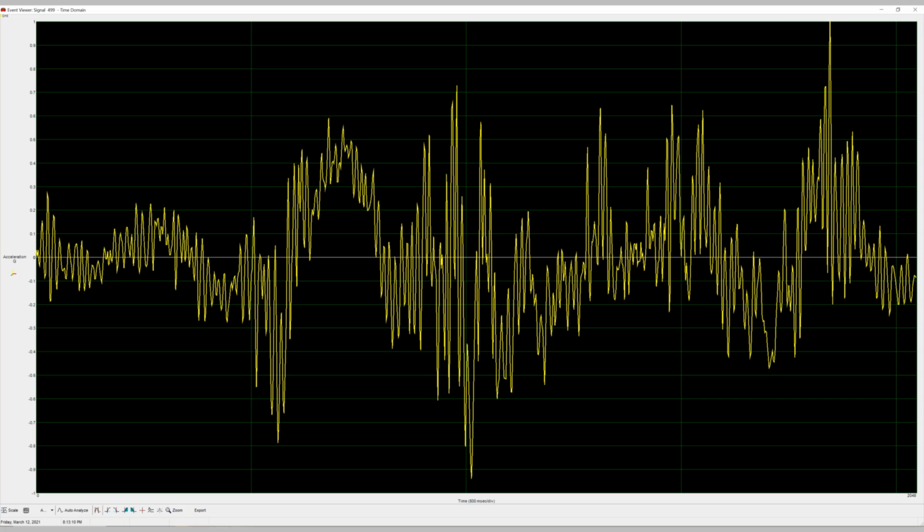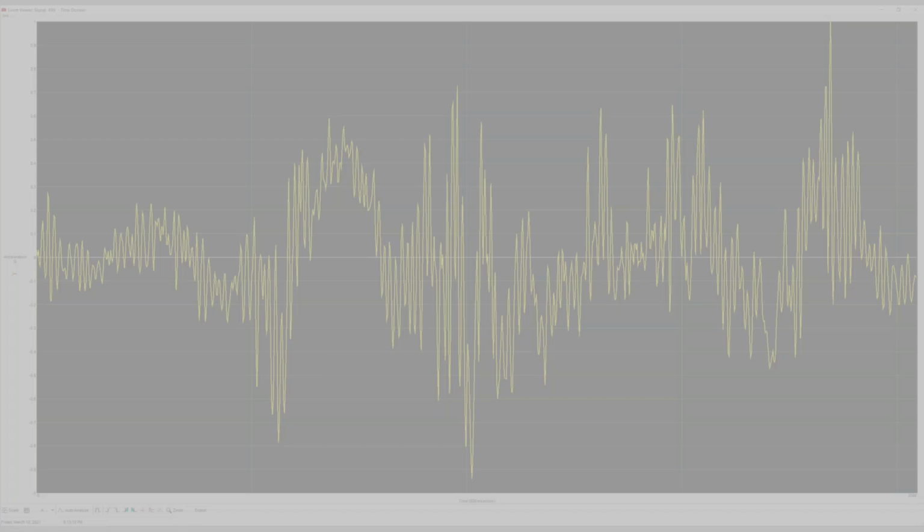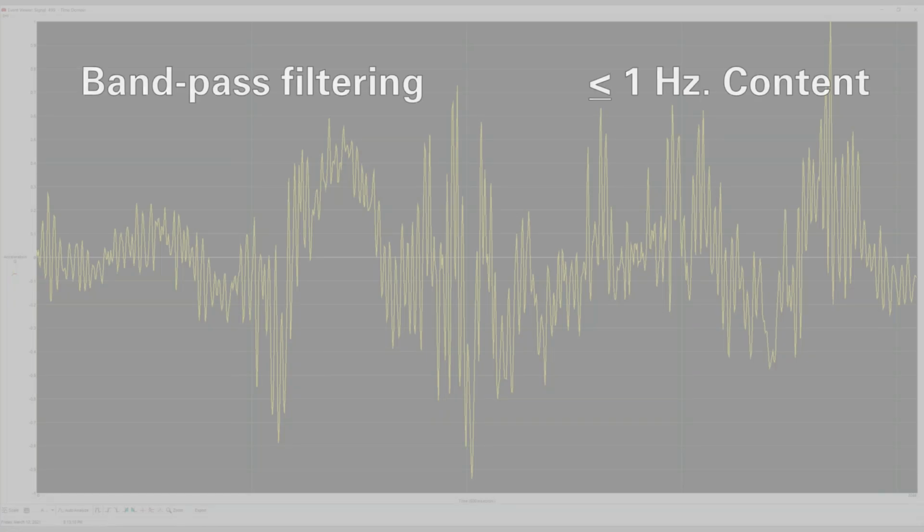It's the same signal I showed in the previous ones in the red, but now it's yellow. And this is about 2 seconds worth of data, right? So from left to right, this says time 0. Out here it says 2.048, but basically think of that as 2 seconds worth of data, and the y-axis being amplitude. Well, I can apply things to this, like bandpass filtering, okay?